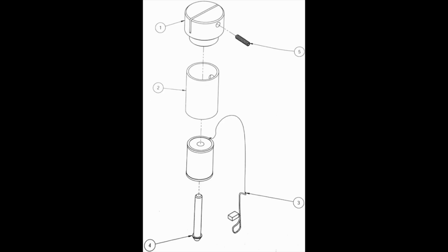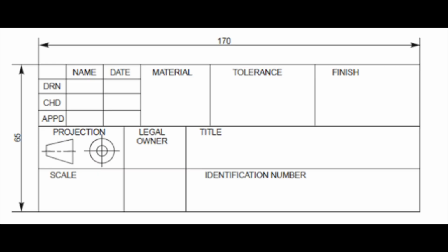This is an example of an assembly drawing. It contains several parts that connect together to form a larger part, and also contains, generally, a bill of materials. Professional engineering drawings also contain a title block with necessary information to identify the part, such as the material, the weight, the title of the drawing, the identification number, the type of projection, the owner or patenting information, the scale ratio, and initials for who drew the drawing and who verified it.